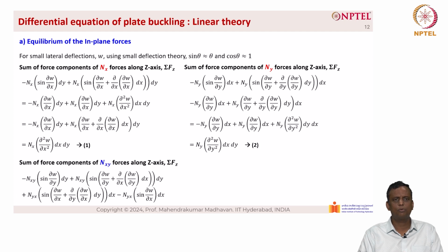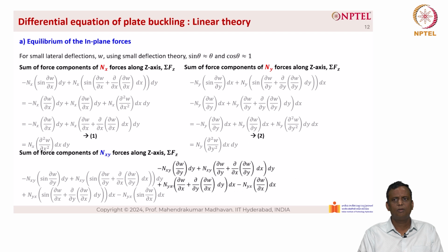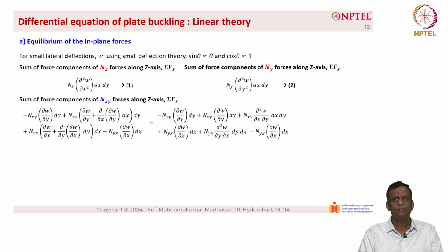Similarly, when we sum the forces of Nxy in the z direction, we have this equation here. We can simplify this further. Some terms get cancelled out. When we do so, we have Nxy into ∂²w/∂x∂y into dx dy plus Nyx into ∂²w/∂y∂x into dy dx.